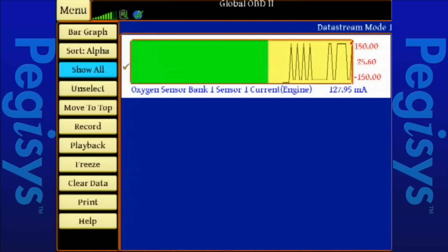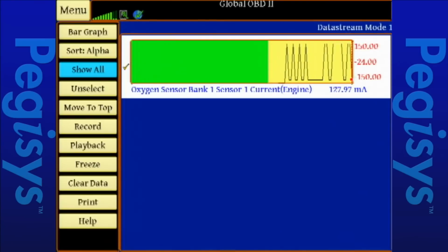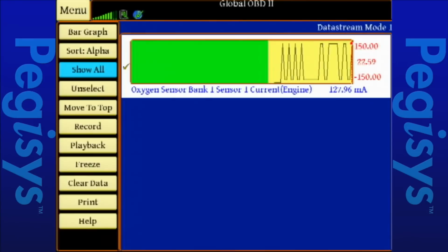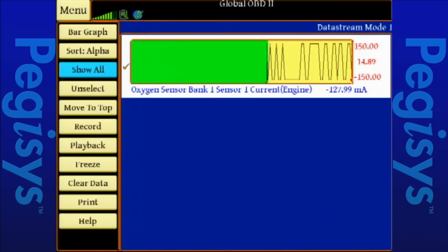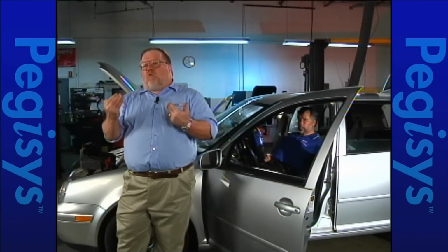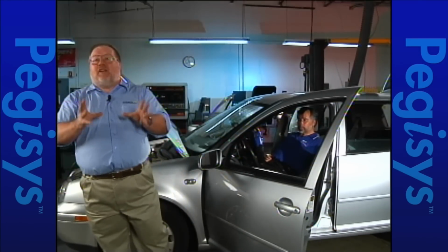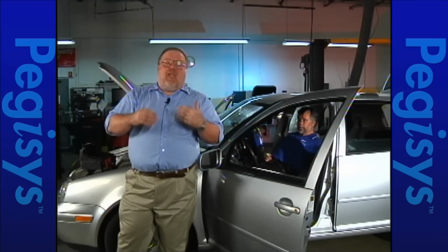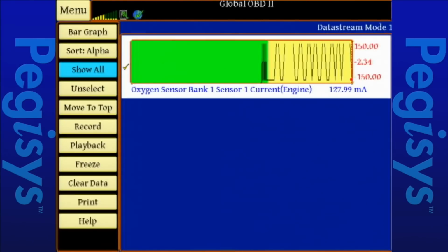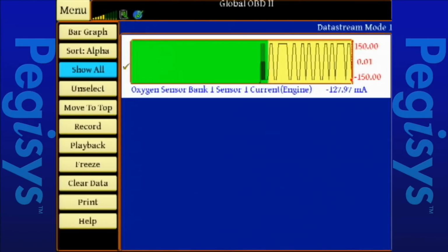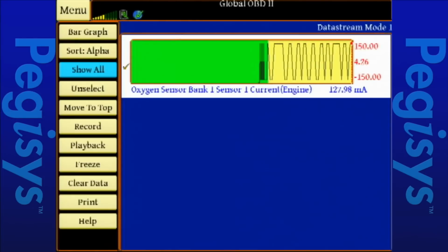If you start looking at this, we've got some spikes on that O2 sensor. But look at the change rate. As we move forward here, you can clearly see that this O2 sensor is all over the place as far as response rate. An O2 sensor that's responding erratically like this is a key component of diagnosis. If the O2 sensor responds erratically, we can run into a situation where it's not going to be allowed to test, or it won't do the testing properly. Now, the sensor starts off very, very slow. And as we change the speed and keep the speed up, as it heats up and begins to burn off, the response rate starts to come back closer to normal.